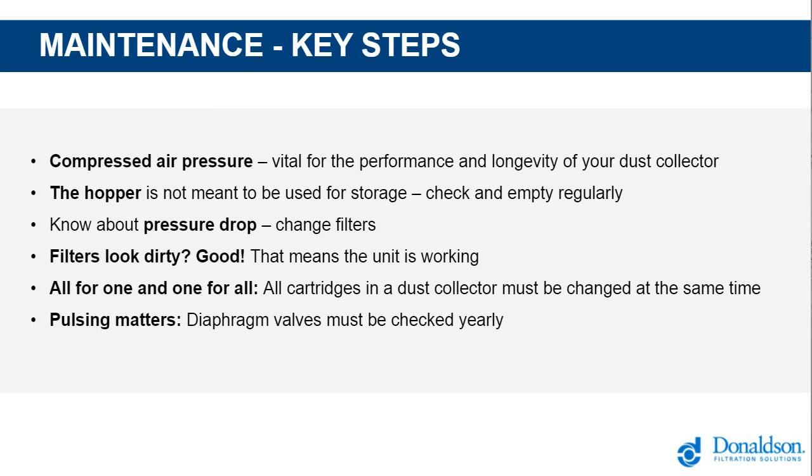And then also know about pressure drop and when filters are required to be changed. And earlier there was a very nice chart, a graph showing when is the appropriate time to change out. And then also looking at the filters, in effect, the cartridges themselves. Do they look dirty? Well, that's good. That means that the unit is working. But really, take that as a cue to keep things in check at that point.